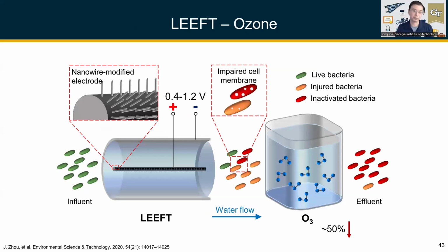Also, as I mentioned, we have combined this LEEFT technology with conventional water disinfection processes. For example, we combine it with ozone treatment. The idea is that in this case, we don't apply a very strong LEEFT, so it can be a lower voltage. The LEEFT process won't be able to kill the microorganisms directly, but it will weaken the cell membrane, making the cell membrane much more permeable for other disinfectants. So in this case, we can use about 50% of the ozone dosage compared to the normal dosage and realize similar